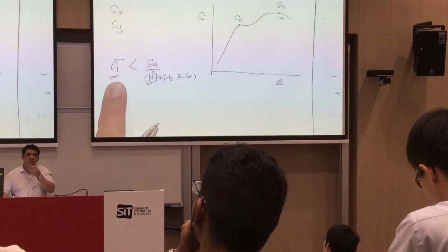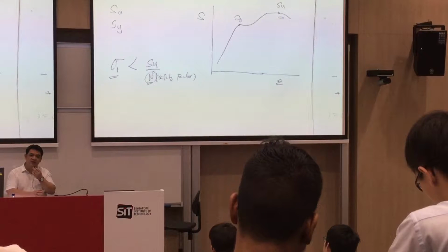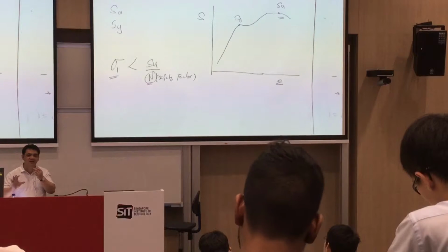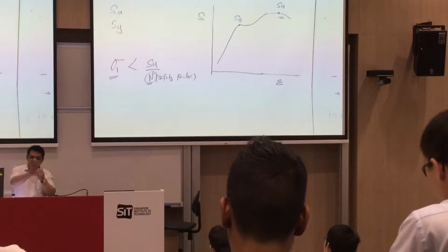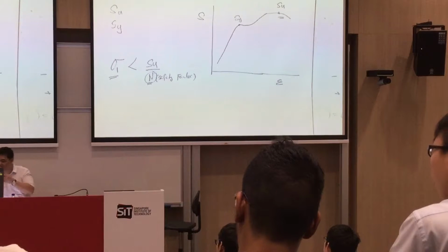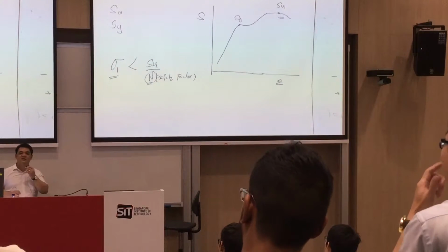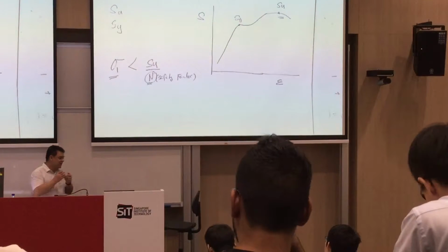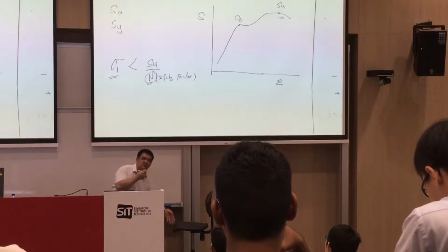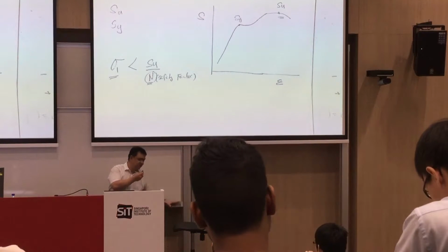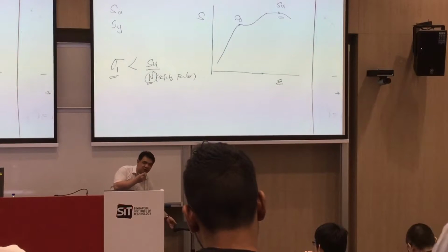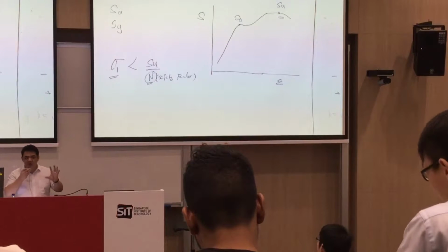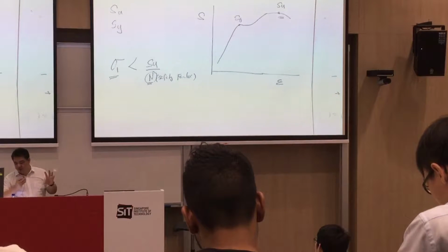So this one, we either calculate using the elementary mechanics and calculation, or finite element if the structure is complex. Right? Probably a simple beam, we can calculate the stress, but if it becomes a chair like that, then it becomes quite difficult, and let's simplify it. So you have to use finite element just to be able to know where the critical section is. Of course, using finite element for this one is really an overkill, so most likely more complex structure with finite element will be useful. So what we're doing at the moment is just, we have our state of stress.